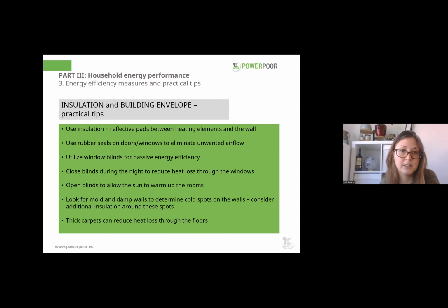So in terms of insulation and building envelope, I already mentioned the reflective pads with insulation that you can use. You can also use rubber seals on doors and windows if you have this unwanted airflow. This is actually a €20 maximum investment and can improve very much the indoor comfort.